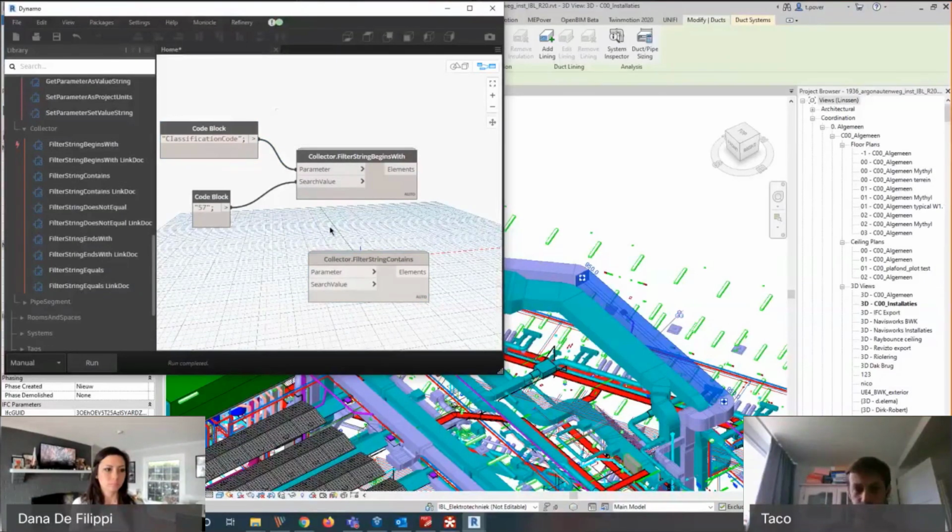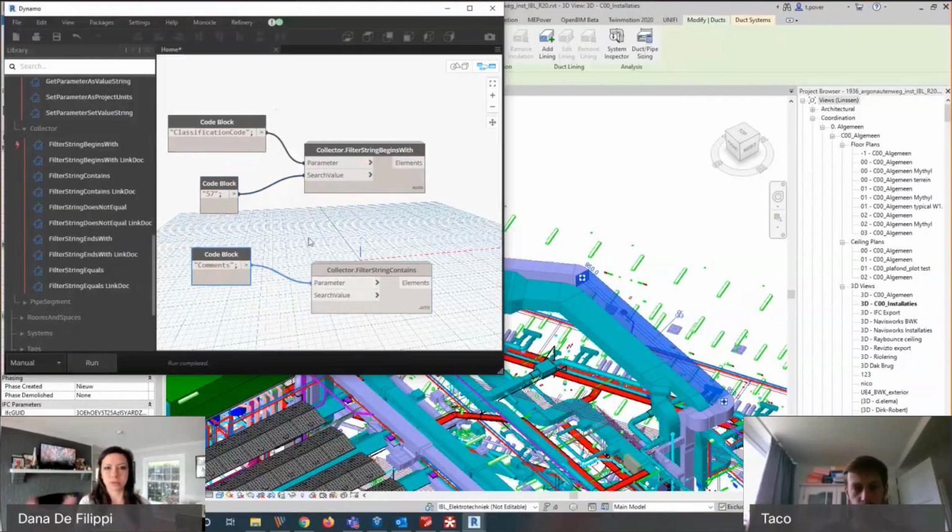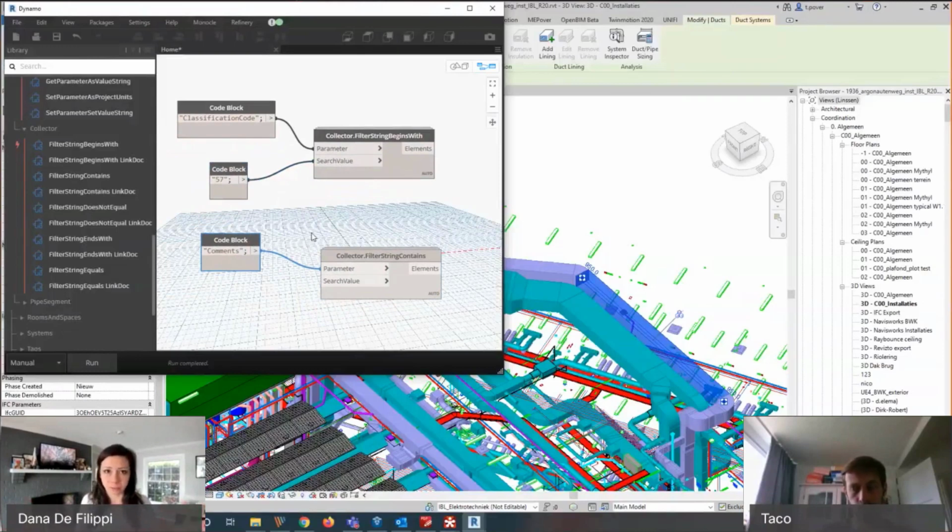and does not work with non-shared parameters. But I really think you should use shared parameters for most of your important parameters. Absolutely. I'm thinking about all kinds of different use cases that I could do with this. I mean, essentially, this is treating a group of elements as a group, right? You could give all of your elements a consistent parameter value across multiple categories, and then treat all of those elements like a group.